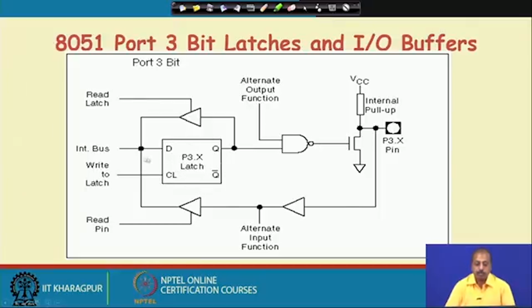Whenever you are outputting some data from the data bus, you can put it into this latch. As a result, until you write something new onto this latch, the processor need not bother about what value it has to output onto the pin.